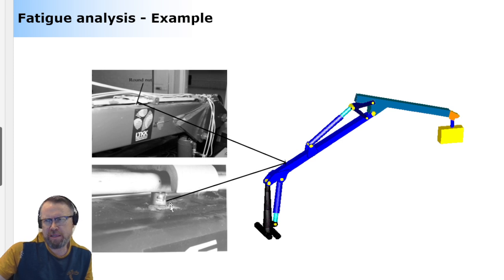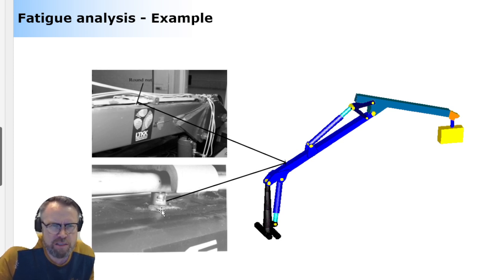Whenever you use welding, you need to understand that it comes with a risk. So what you really want to do is take the welding as far as possible from the highly stressed area. And when you look carefully, this area happened to be the most stressed. This is where you can see that obviously the highest stress is located here.